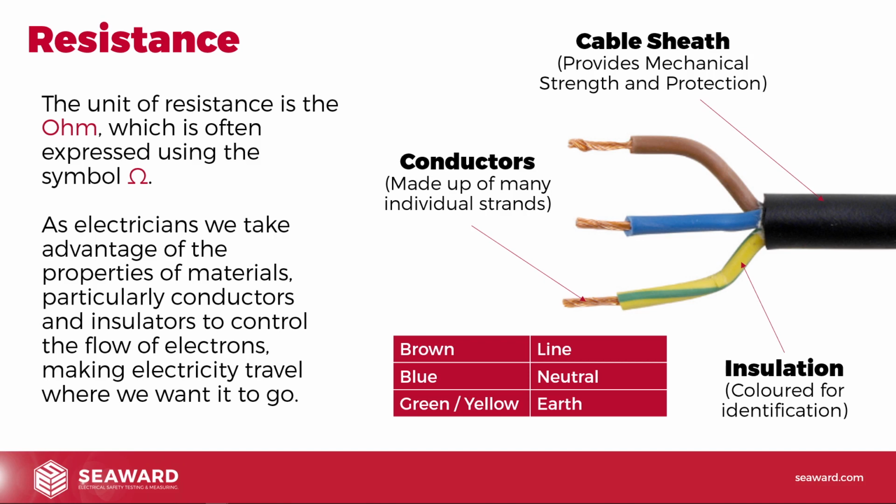So that's the protective conductor, and that's generally used in Class 1 equipment as the protective conductor. We do have Class 2 equipment, and we'll get onto this in future sessions, where it only has two wires in there, the line and the neutral. So there might not be an earth in all of the cables, but where we've got a 3-core cable, generally we'll be looking at a brown line, a blue neutral, and the yellow and green cable is the earth.